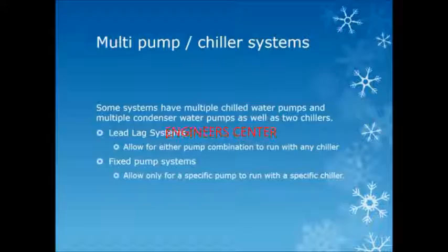Some systems will have multiple pumps as well as multiple chillers. These systems are often configured in a lead-lag system, which allows for either pump combination to be run with any type of chiller or any one of the chillers. The fixed pump systems will only allow for a specific pump to be run with a specific chiller.